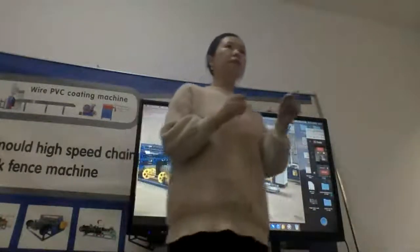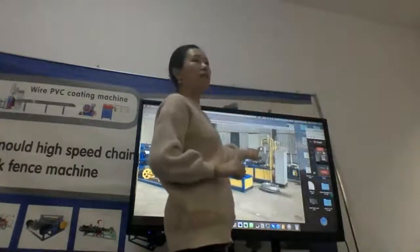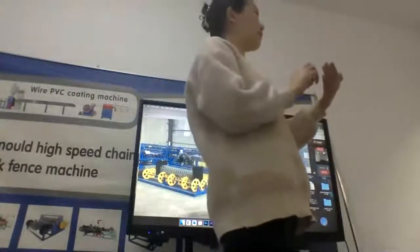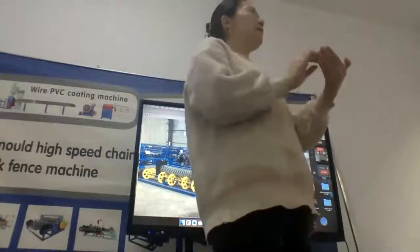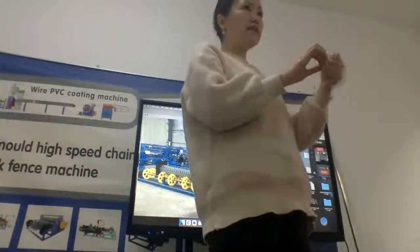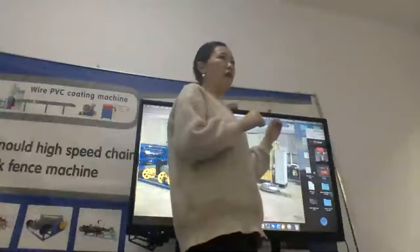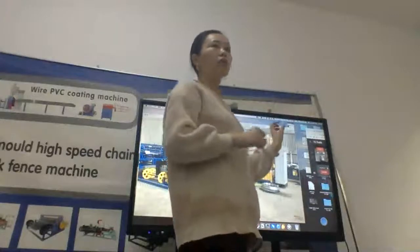If you use the speed reducer, you can change the ratio by inputting the ratio number on the touch screen. Why do you need to change the ratio? Because sometimes you use galvanized wire to produce the chain link fabric, but maybe sometimes your customer wants stainless steel wire. Stainless steel wire is very hard, so you need the machine to be more powerful. This time you may need to change the ratio. So if you use the speed reducer, you can change the ratio easily on the touch screen.